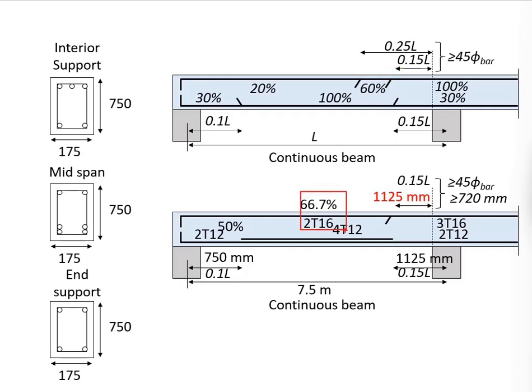The provided amount of reinforcement bar is still greater than this 60%. As you cannot reduce the rebar further, we will stick to this 2T16 towards the end. Although the requirement here is only 20%, unless you reduce the bar size some more with a proper lapping, you may stick with 2T16 throughout the span.